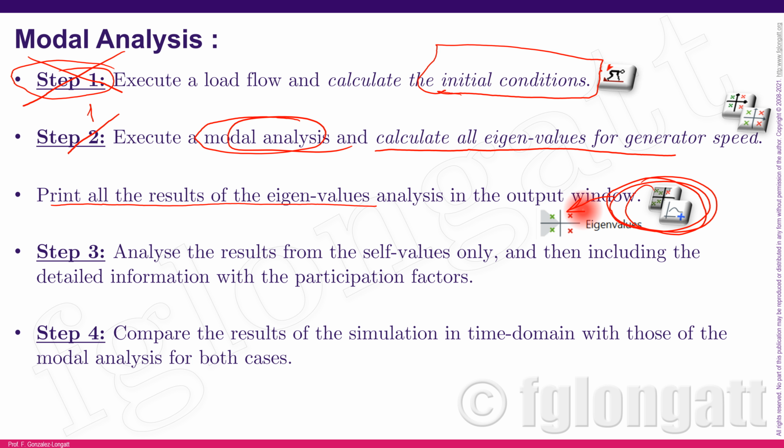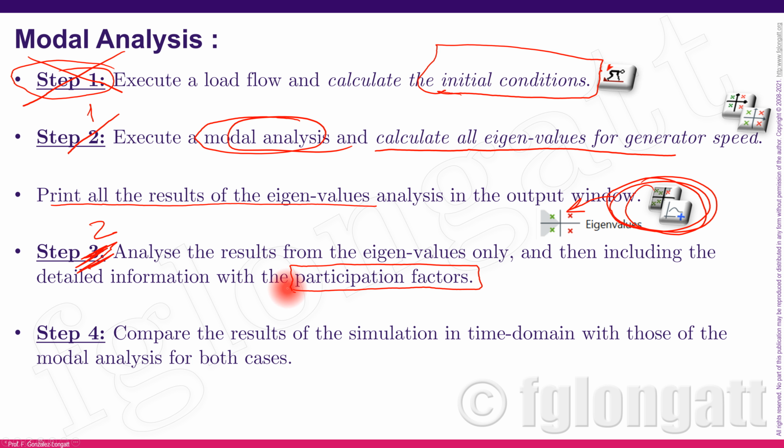Then, if you want to do the step number 2 using PowerFactory 2021, you can analyze the eigenvalues by using many tools. For instance, PowerFactory includes what we call the participation factors, okay? Participation factors, if you remember my class, are one way to estimate how important one specific oscillation mode is in the whole oscillation, okay? How a state variable is participating in one oscillation mode, okay?